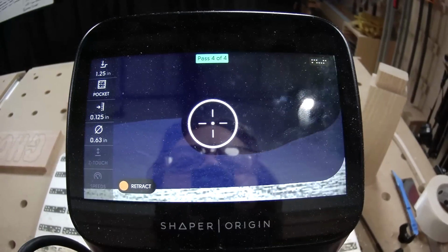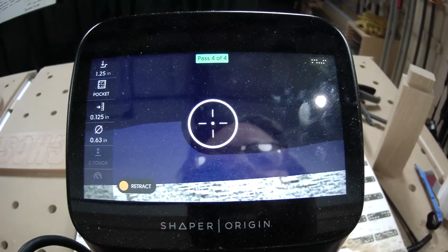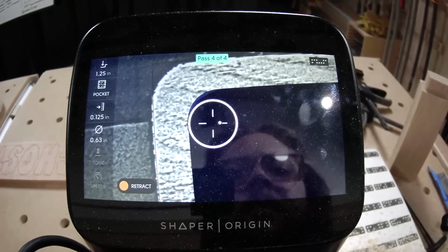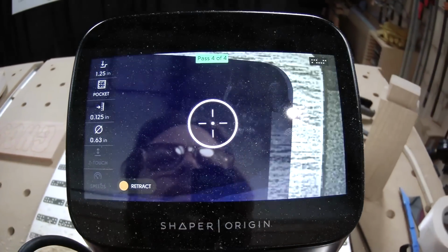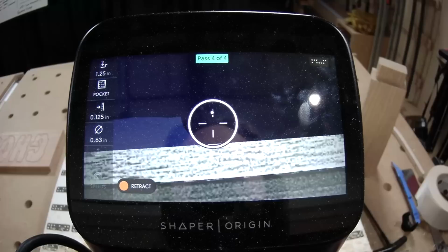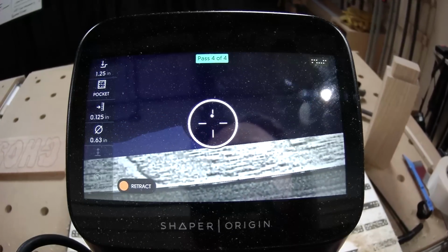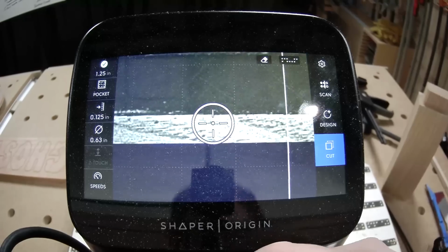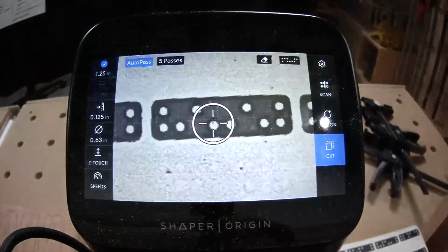I think one of the things to remember is, just like we do roughing and finishing on the diameter of a shape, you can also do roughing and finishing on your depth. So we could clean all this out to a little bit less than our final depth, and then we can make it a little deeper, just take a small pass, and we're going to get a better bottom finish quality than if we try to take a full chunk at the end.